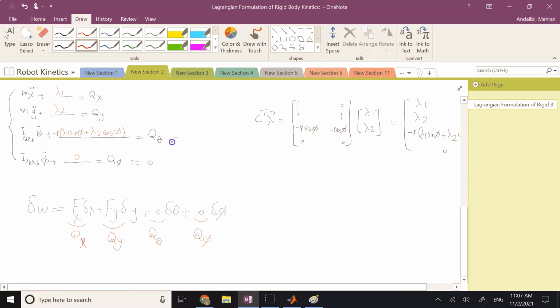So here, and there we go. We got our equations. Now, do we have enough equations for all of the unknowns? So if I ask you what are the unknowns, in this case, your unknowns, there are 6 of them. There is x double dot, y double dot, theta double dot, phi double dot, as well as lambda 1 and lambda 2. So you need 6 equations, but guess what? We only have 4 equations so far from Euler-Lagrange.